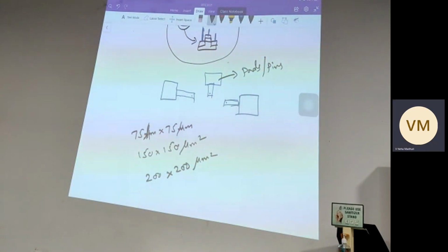And similarly, the source of the transistor has to be given to the ground. That means two wires or two connections will come out from your power supply or battery, which has to be connected to your drain and source. And then input, from where will you give? You have seen a function generator in the lab, right?